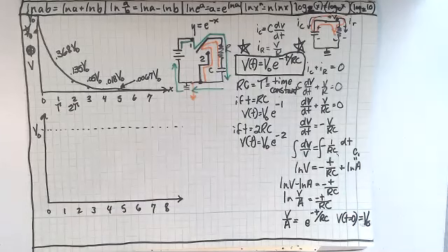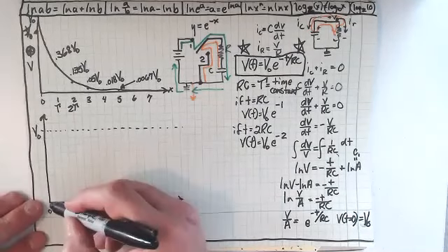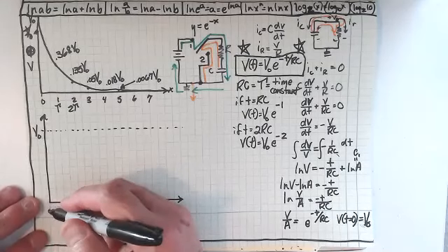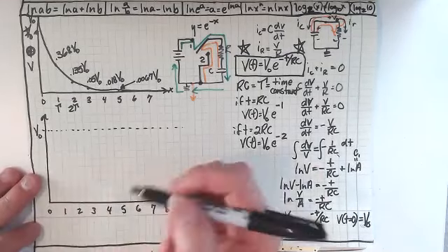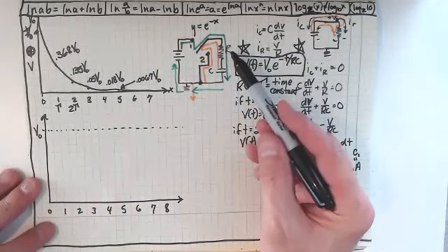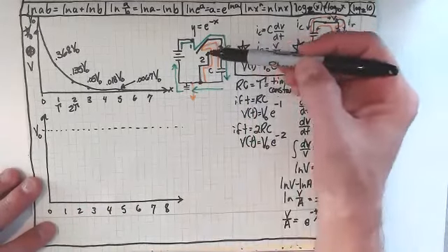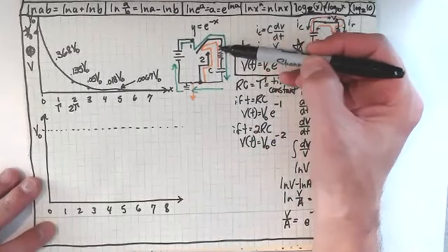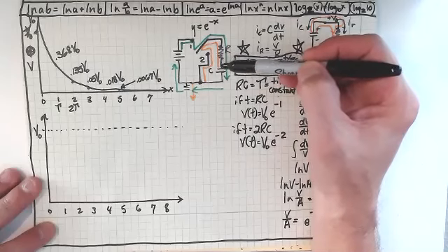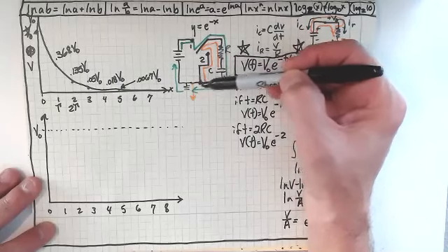So when I'm charging a capacitor, the voltage on the capacitor starts at 0, right? There's nothing there. But as I start to run current, actually I'm not running it through the capacitor, but I'm running it onto this plate, and that's pushing the other electrons.